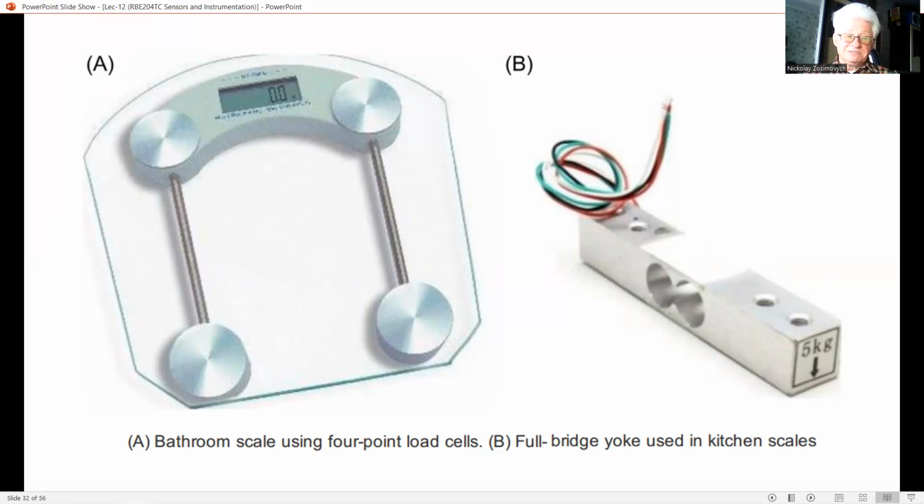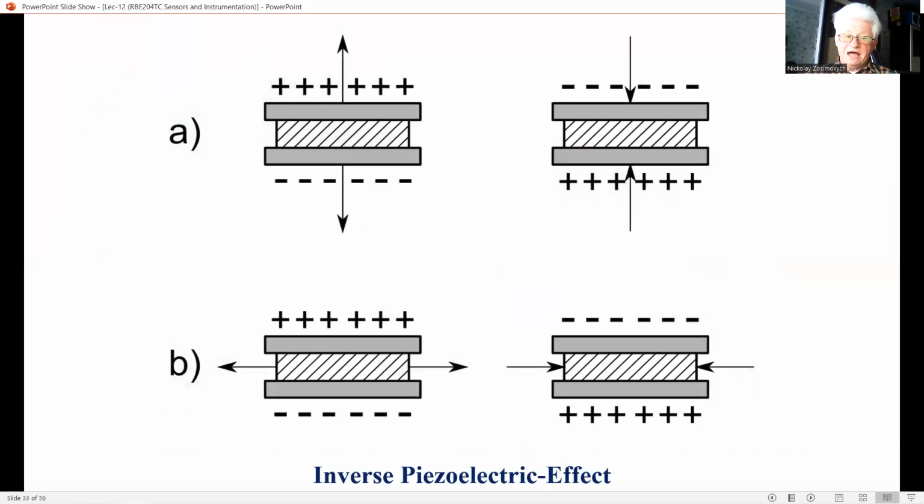The reversibility of the piezoelectric effect provides solutions with a combination of actuation and sensing. Sometimes such a combined piezoelectric sensor actuator system is used to reduce vibration that may occur in precision mechatronic systems. In this example, a wafer stepper.